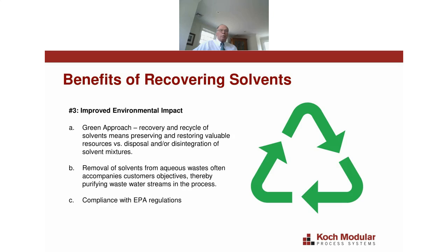And it's very common for us, in addition to supplying a solvent recovery system, to supply a steam stripping system to recover the solvents out of their wastewater. And then the solvents that are recovered from their wastewater are combined with recovered solvents and go through the solvent recovery system. And obviously, having a solvent recovery system makes it easier to comply with EPA regulations.